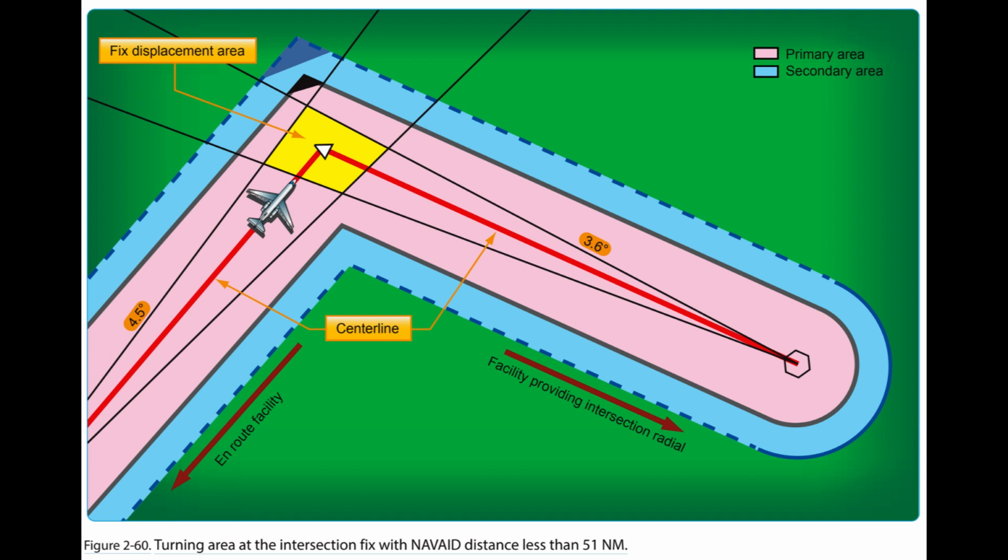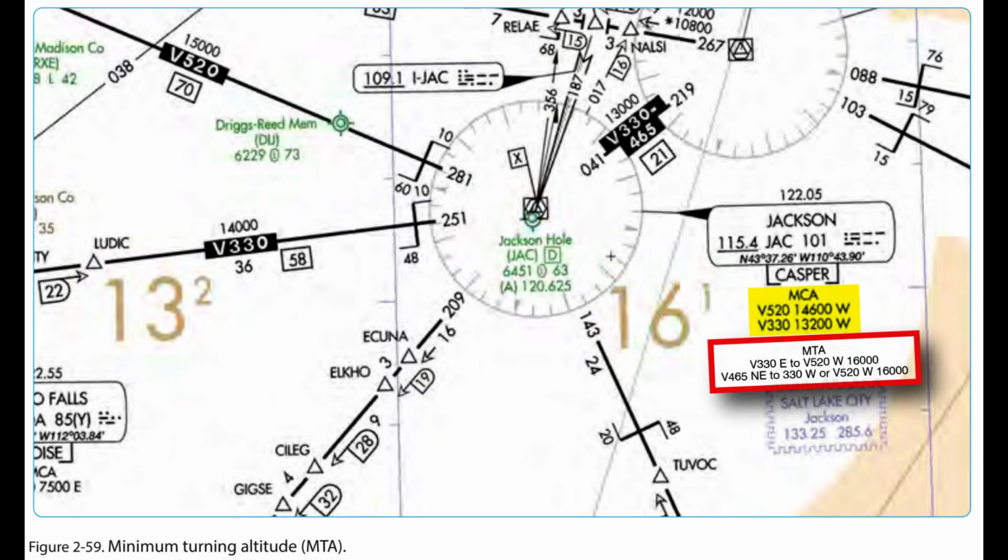Figure 2, 60. Due to increased airspeeds at 10,000 feet MSL or above, an expanded area in the vicinity of the turning fix is examined to ensure the published MEA is sufficient for obstacle clearance. In some locations, normally mountainous, terrain/obstacles in the expanded search area may obviate the published MEA and necessitate a higher minimum altitude while conducting the turning maneuver. Turning fixes requiring a higher MTA are charted with a flag along with accompanying text describing the MTA restriction.